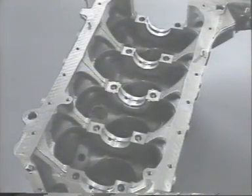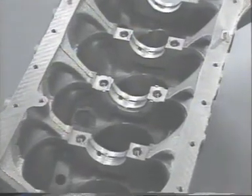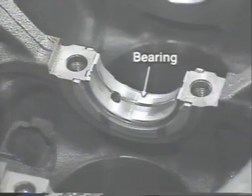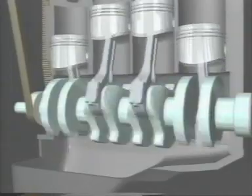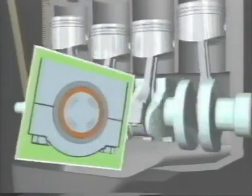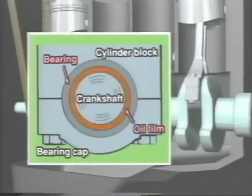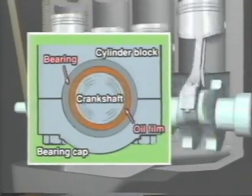The crankshaft bearings receive the impact load of the explosion applied to the rotary parts of the crankshaft, such as the journals and crank pins, as well as the loads of these parts themselves. An oil film of an appropriate thickness is formed on each bearing surface to prevent seizure of the rotary parts and minimize frictional damage to them.